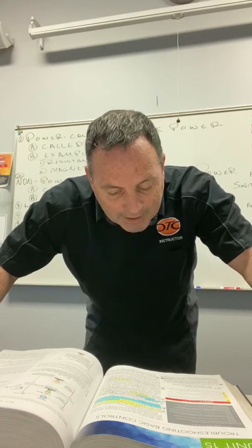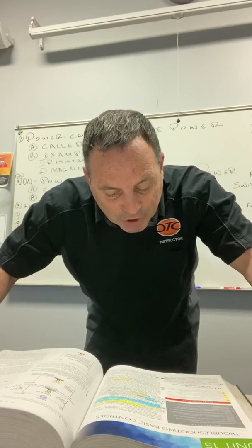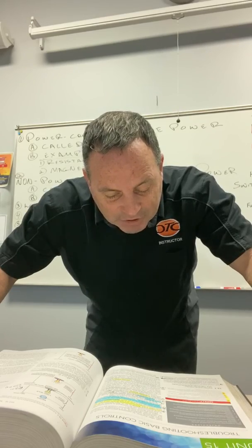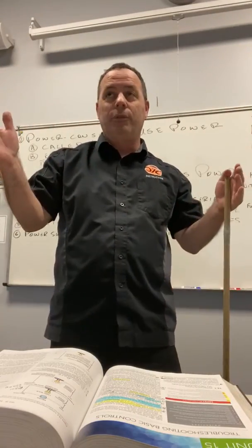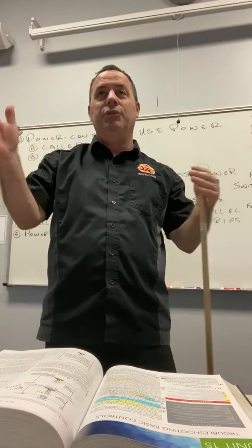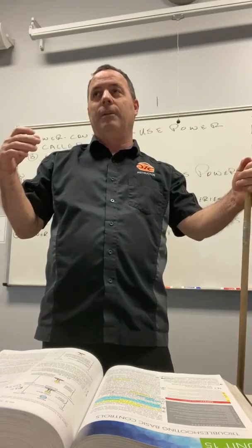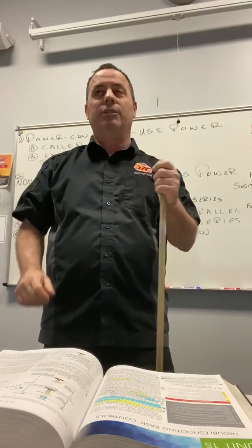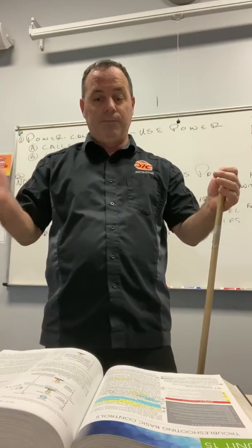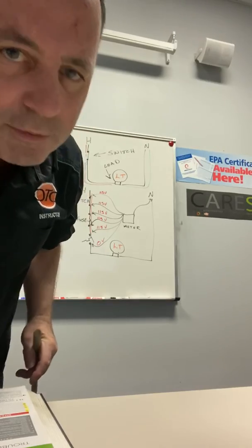Notice this: for any power consuming device to consume power, it must have potential across it. Potential voltage is the voltage indicated on a voltmeter between two power legs. So hot and neutral could be 24 volts. Hot and neutral could be 115 volts. Okay? If it was two-phase, you would have 120 and 120, so your potential voltage should be 240. Now, we talked about this the last couple of weeks, so I think you pretty much understand that, so I'm not going to keep discussing the same exact thing with you over and over.